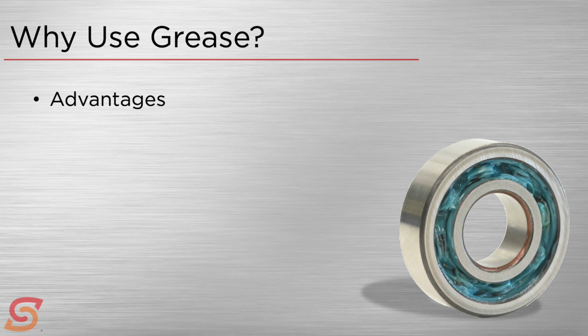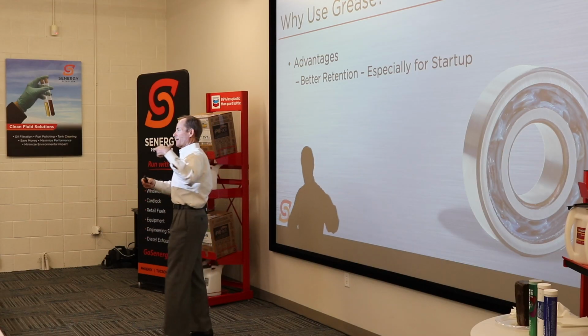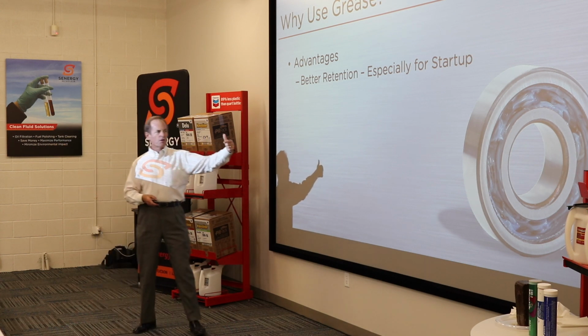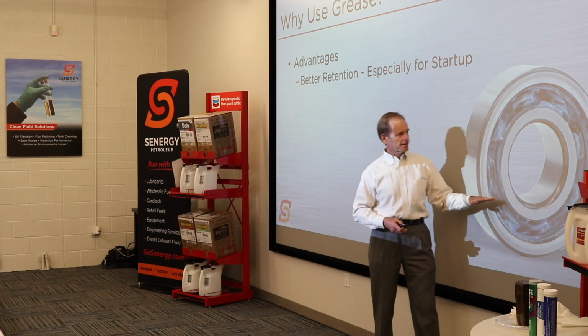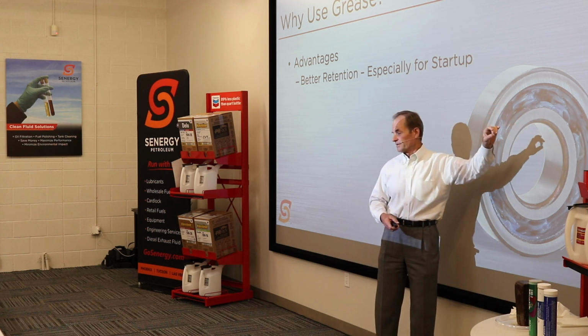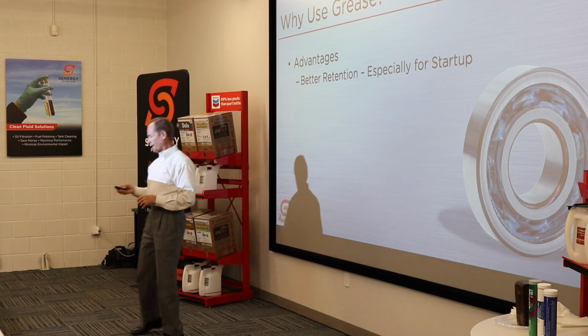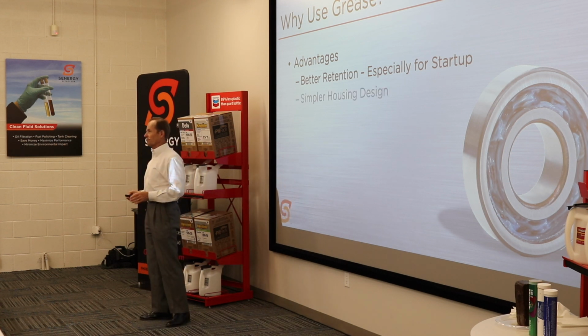Well, the advantages of greases include a number of things. The first is the availability of lubricant at startup, all right? Imagine you've got a bearing sitting still in a piece of equipment. When you first start moving that piece of equipment, you've got lubrication there. If this were an oil lubricated bearing, it might be sitting in a bath of oil that's this thick. But this whole area up here is not lubricated. It has to get moving to get lubricated. Or you might have to have a pumping system, pumping oil there to lubricate it. So grease starts out where you need it. That's the first advantage of grease over oil.